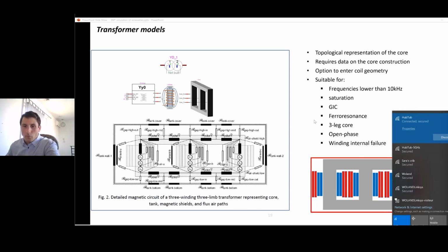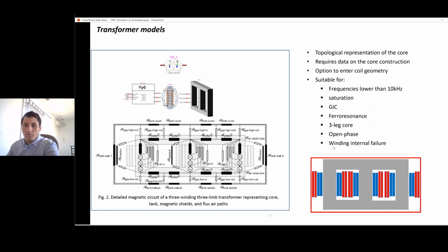So this model is also suitable for resonance, open phase, winding failure. You have the possibility to model in detail all coils and to do internal faults.